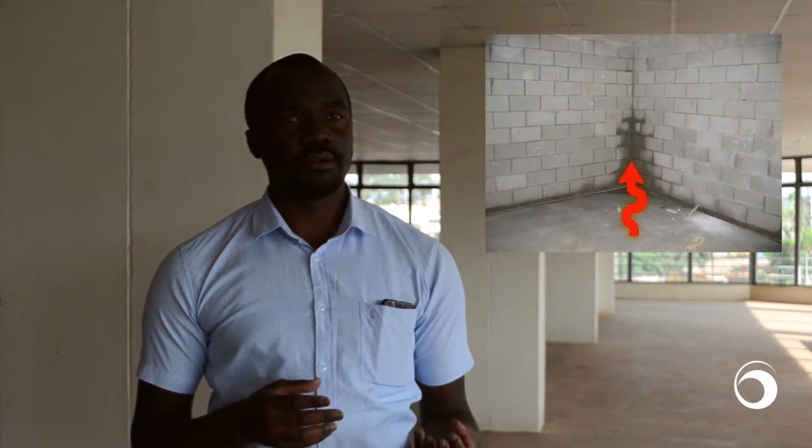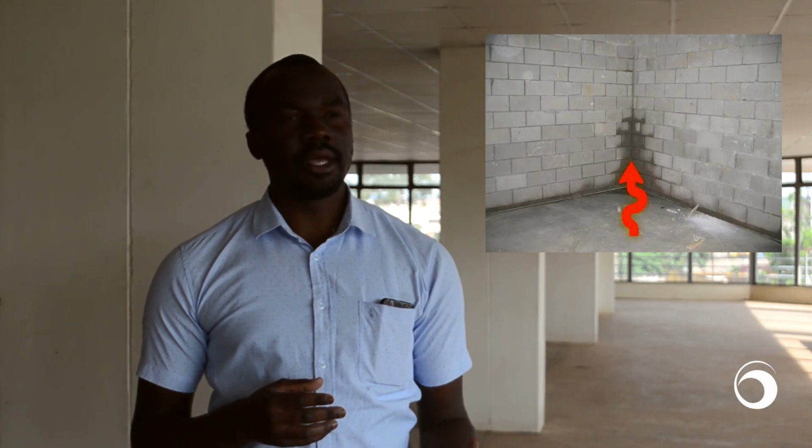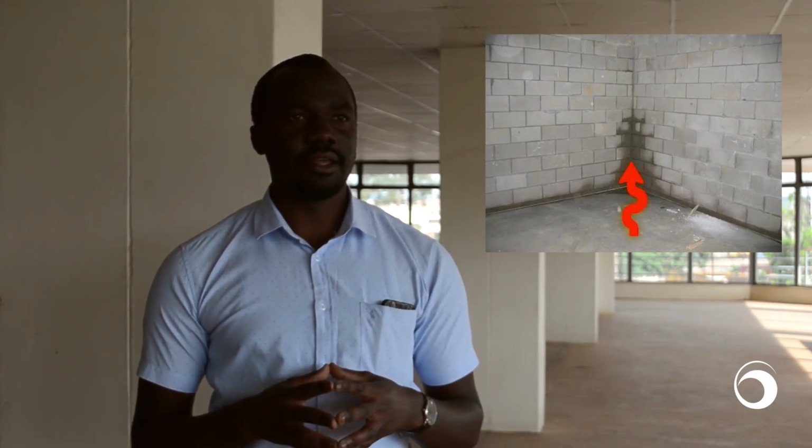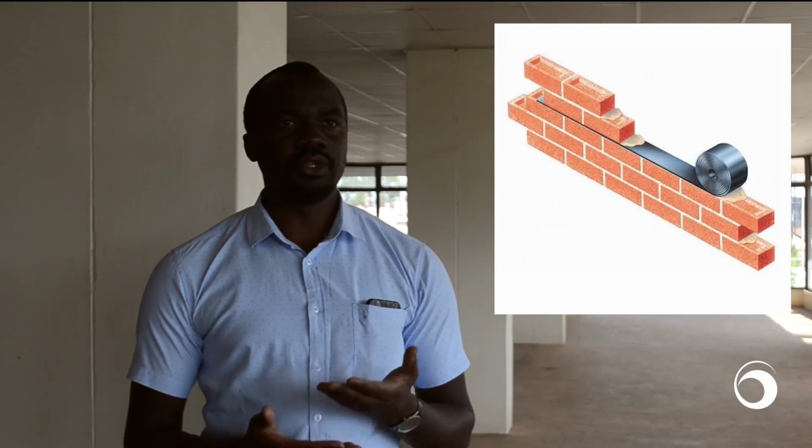It's as a result of water from the ground making its way up the wall, and the problem of that, it would affect all the finishes you have on the building. In that case, you need to investigate, or again, I would advise that you consult to find out where the problem is. In some cases, it could be a result of not having a damp-proof layer or membrane between the upper wall and the foundation wall or the slab of the building. So the rising damp is actually getting from the ground and coming up. In other cases, it's as a result of splashback from a building.